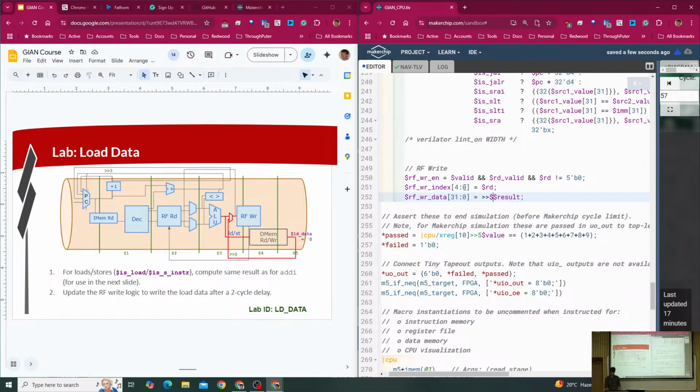So if it is a load and 2 cycles ago, then we want to write the load data also 2 cycles ahead in the pipeline. Otherwise, we want our default behavior. So in the case of load, we have created the shadow. So the instruction 2 cycles later is not trying to do anything else. We'll use that time to inject the load data.